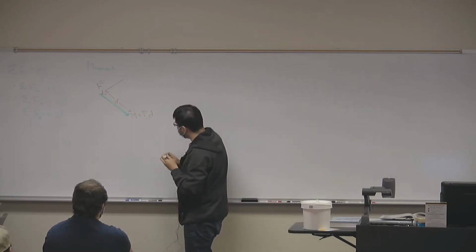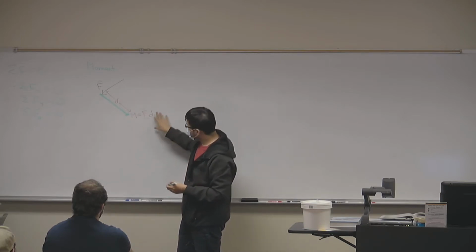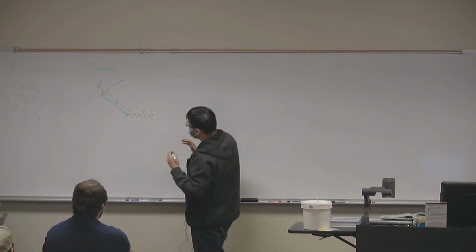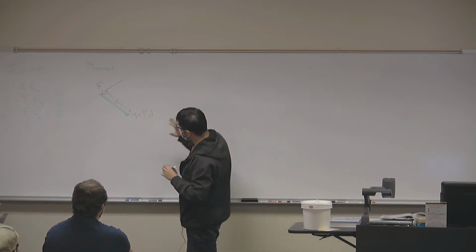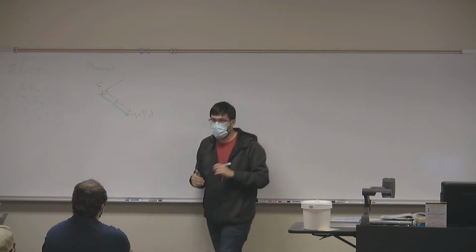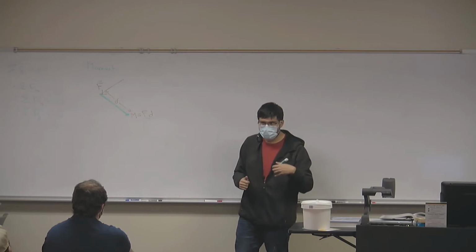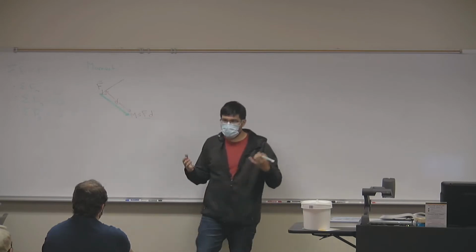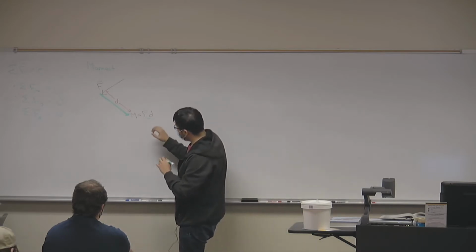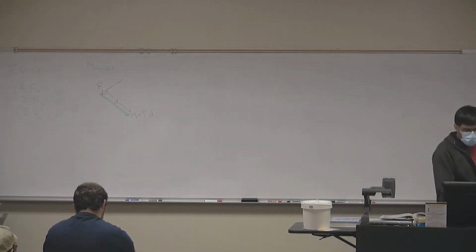And what does this tell me? The further away my force is from my point of interest, that means the greater my distance, and so the greater my moment. So what this tells us is that with forces, we don't only have to care about their magnitudes, but we also care about where in my body they are applied. When I say body, remember week 1, I mean an object that consists of multiple particles together, okay? So moment is force times distance. The greater the distance, the greater the moment. The greater the force, the greater the moment.